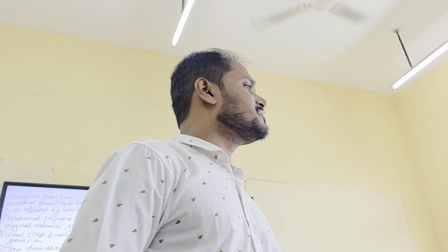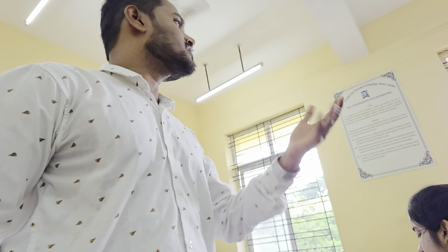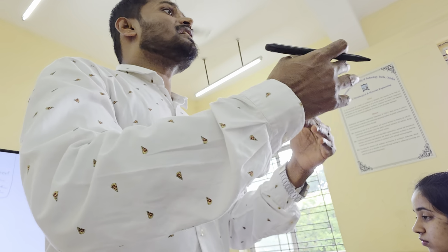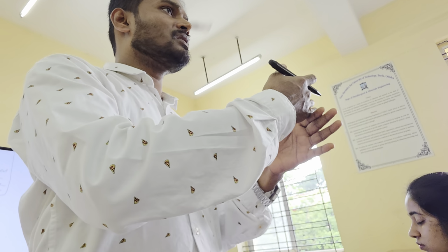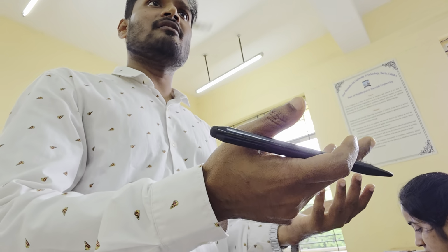What exactly deoxidation means. See, the first stage of production of steel is iron making, right? We produce iron from the ore. Because we already studied mineral processing now. We do mineral processing, finally you will get a concentrate of iron ore. That concentrate of iron ore will be extracted, iron will be extracted from that. That is molten iron, pig iron we call it. That molten pig iron is impure because it contains carbon, silicon, sulfur, phosphorus, manganese. Lot of impurities are there.